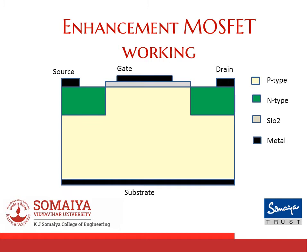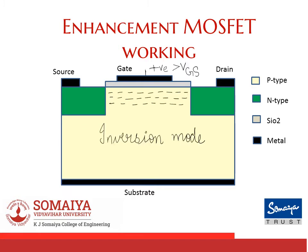When I have an enhancement MOSFET, I'll again be applying all three types of gate voltages and observing what is happening with the device. When I apply a positive voltage, I'll see the electrons being attracted at the silicon and silicon dioxide interface, and that will help me form a channel between source and drain. This channel goes on increasing as you increase the gate voltage.